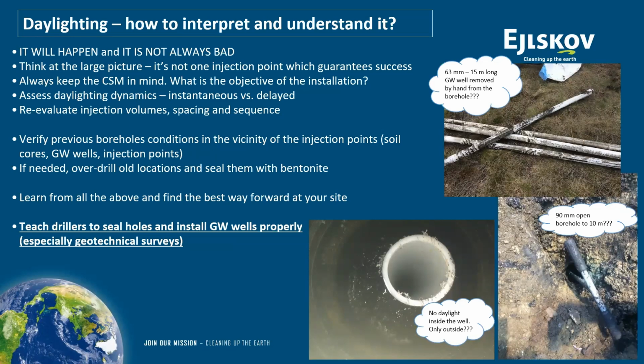As soon as I saw some instantaneous daylighting occurring, I thought something is wrong here. The drillers that came in the very early days at the site never put sand and bentonite around the well. What can you expect when you inject fluids in the area? Instantaneous daylighting. Similarly, you can find in clay formations open boreholes, for example 10 meters deep, which have not been sealed properly.